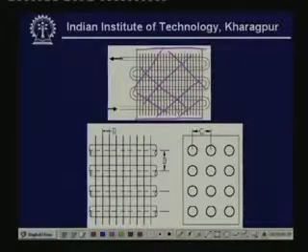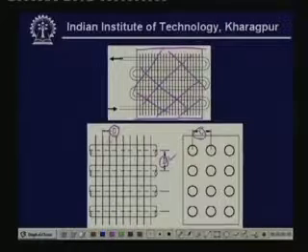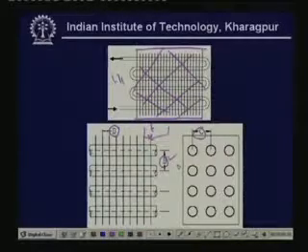And we have also defined certain parameters. For example, as I was telling you just now, B is nothing but the center to center distance between two consecutive tubes in a row, right? This value is given. C is, this is the side view, the center to center distance between two rows, right? So that is C, and D is the center to center distance between two consecutive fins, and T, as I said, is the thickness of the fin, right? So all these parameters are given to us. So we have to ultimately find out the face area, and we also know the face velocity. Okay, face velocity is mentioned as 2.5 meter per second.